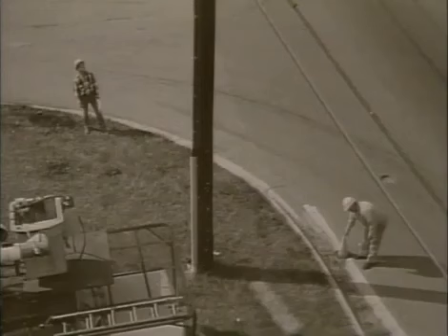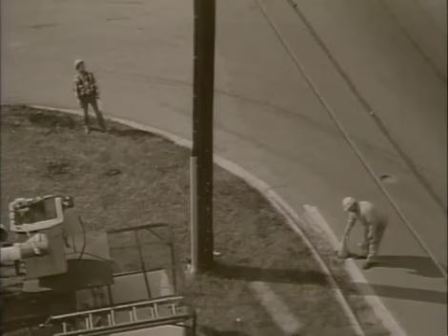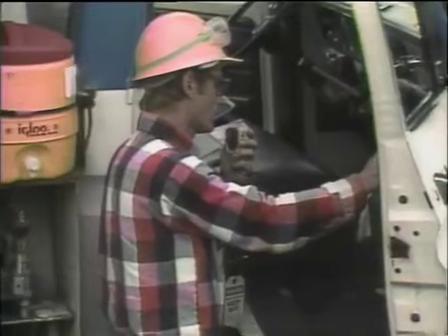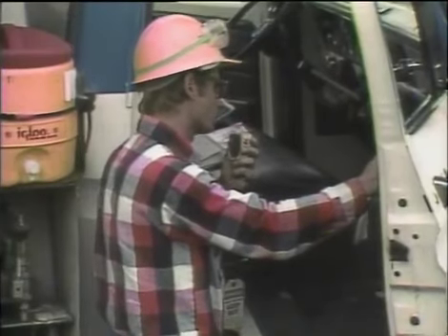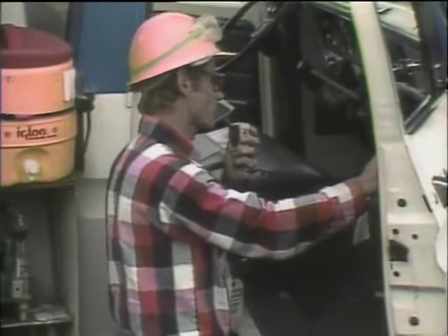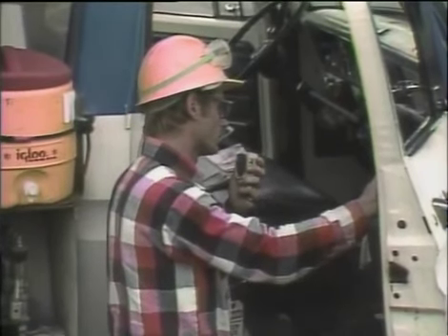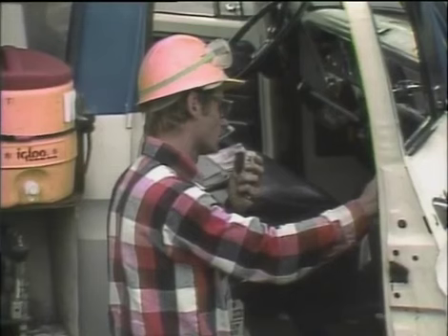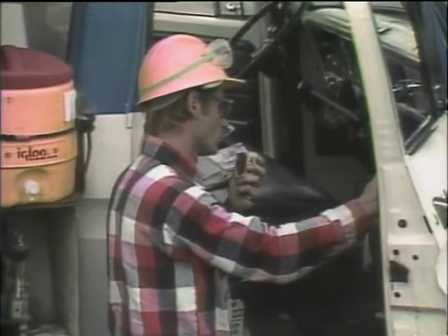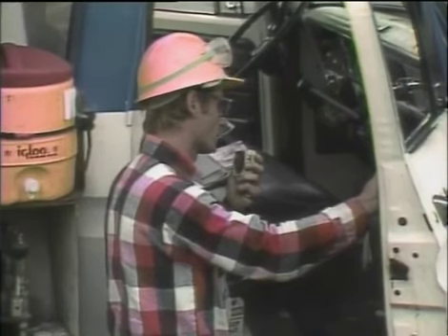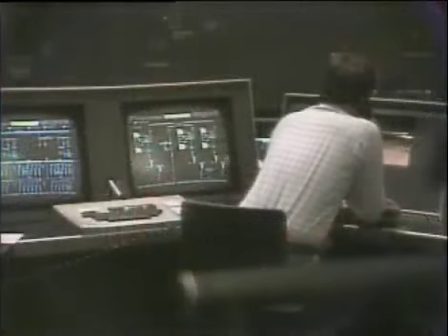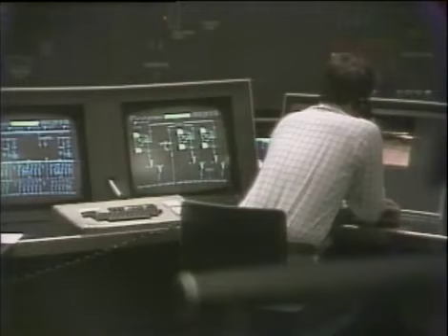When the pole is located in the field, the crew leader checks the components at the job site, while his partner marks off the work area. The crew leader radios the dispatcher to get the go-ahead to proceed with the job. "I'd like to install my tag and grounds on 69069, pole last 4, 9994." The dispatcher gives the crew clearance to test for dead and install protective grounds.